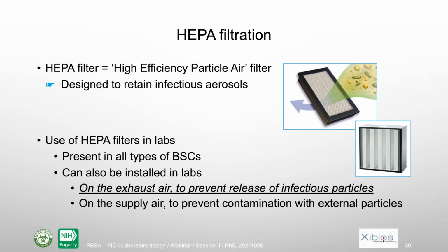And if we want, for instance, to protect the outside population, in that case, we could have HEPA filters on the exhaust of the lab. Sometimes they are also used on the air which is supplied in the lab to prevent contamination with external particles. That's for product protection, and it's used, for instance, in the pharmaceutical world for vaccine production or for different types of clean rooms.